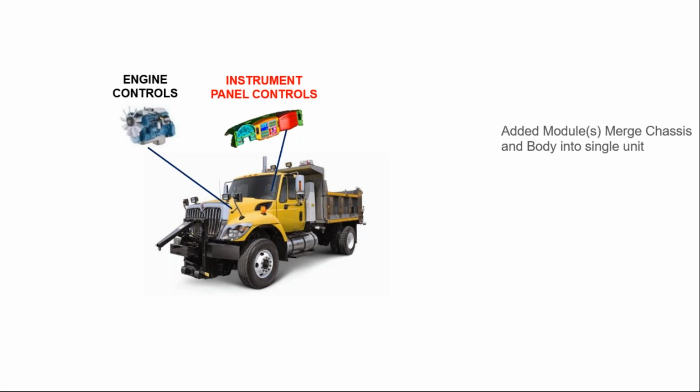In 2017 and up, they talk on a new data link. So when a driver pushes a switch, information is sent down a data link to the body controller, as I mentioned earlier. If it's a pneumatic type device, it's going to turn that solenoid on or off to control possibly a PTO or air ride suspension or whatever an upfitter may install.